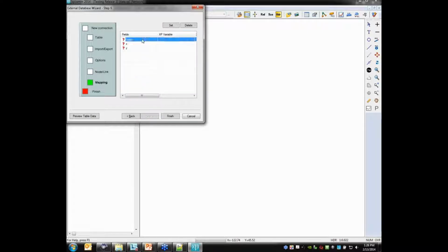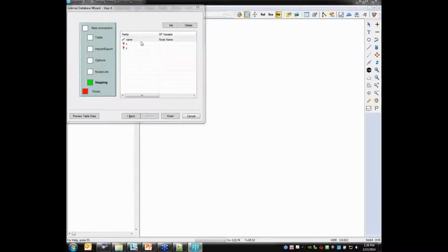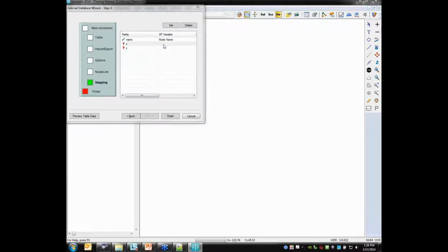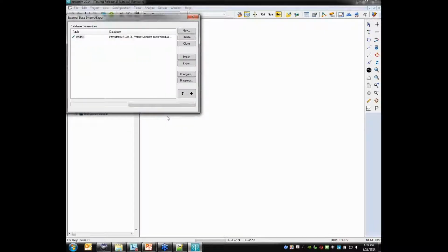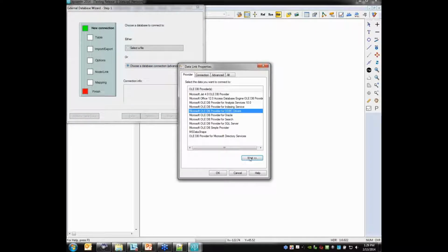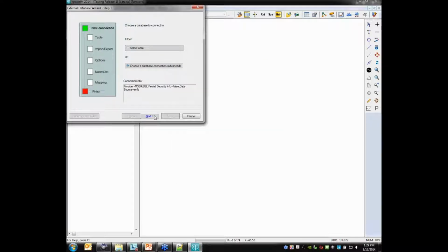I'm going to go ahead and map those fields here as well. Now you may ask, why do I have to map it once in node and link and then once in mapping? It has to do with whether you're reading it strictly for generating the geometry or you're actually writing it to the database. I typically write it there anyway. You'll get some warning messages because that's something that can't be overwritten, but it's worth it when you're trying to build geometry. So let's go back here and add links.